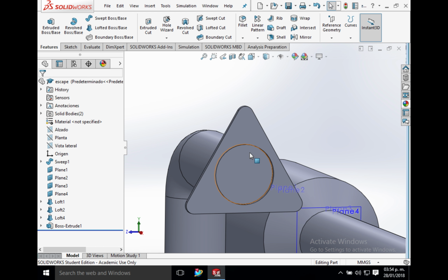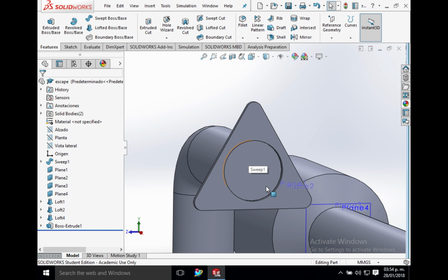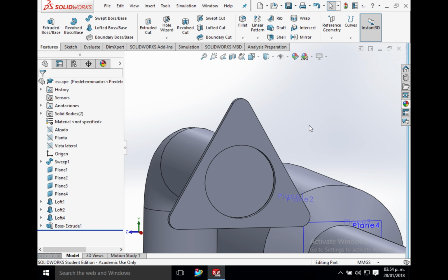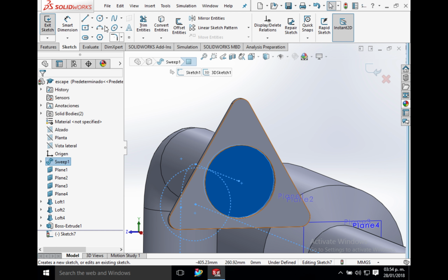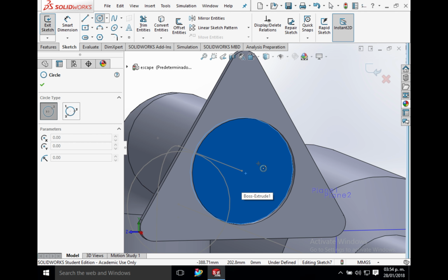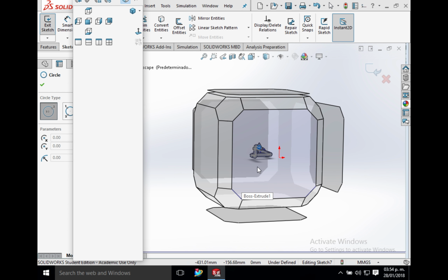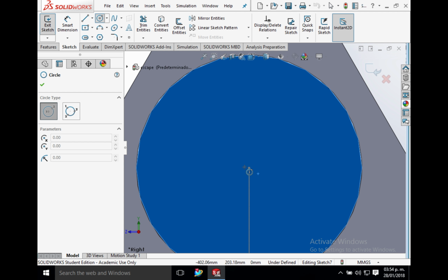Now we want this kind of cylinder. That's supposedly our tube. We want it to actually be a tube with some air here. So you're going to click here, select sketch, then you click here, and well, let's move this shape so it's easier. And here at the center, you create a circle.